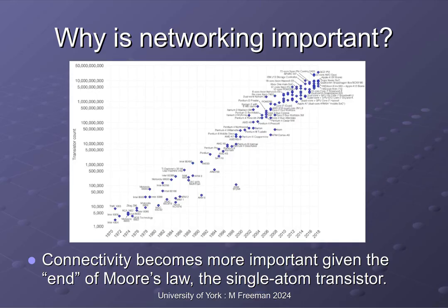The downside to that is that eventually you get very hot bits of silicon. Every time you get a clock transition, you dissipate a little bit of power. And obviously the more clock edges you have per second, the higher the frequency, the more power you dissipate and the hotter they get until they melt. So there's a fundamental limitation for our silicon technology.